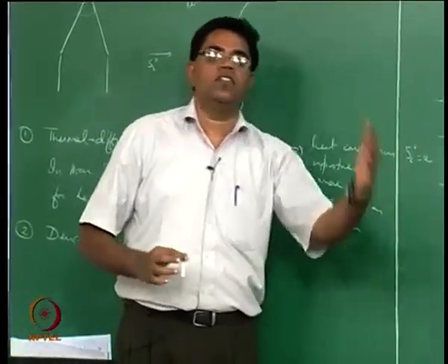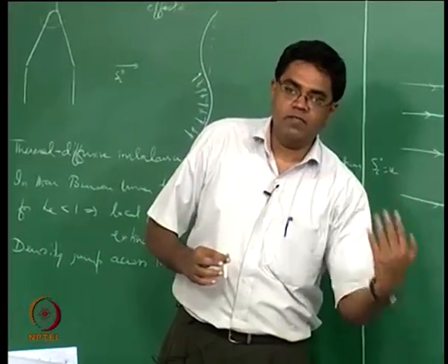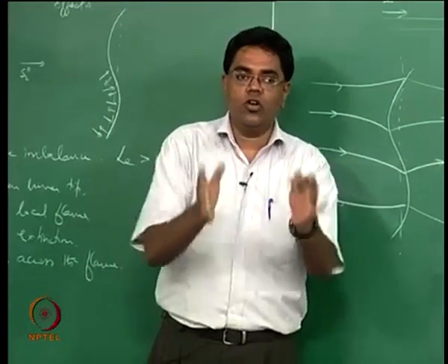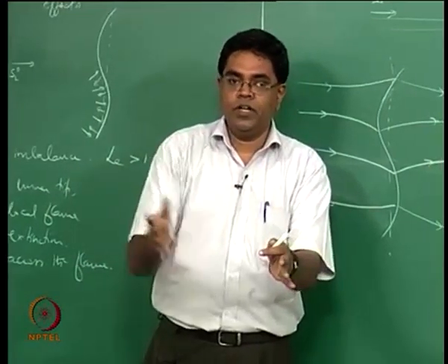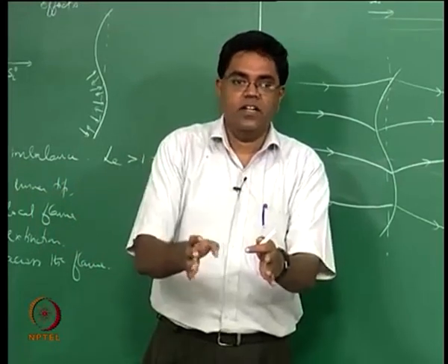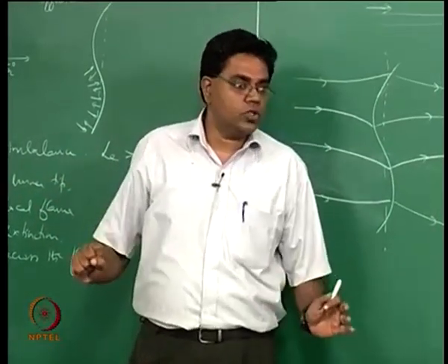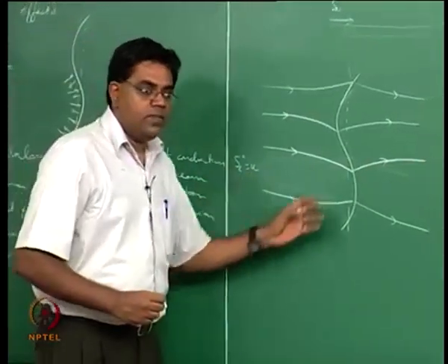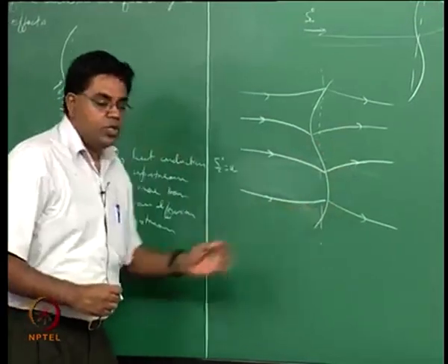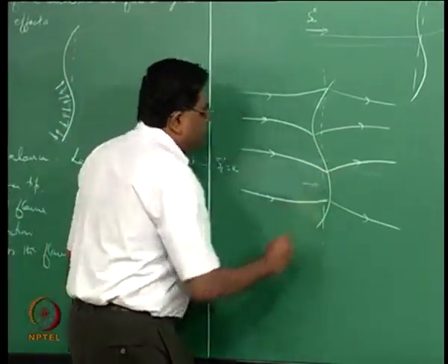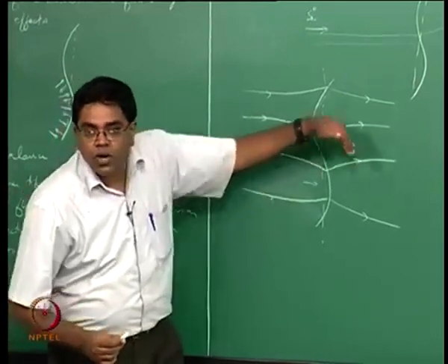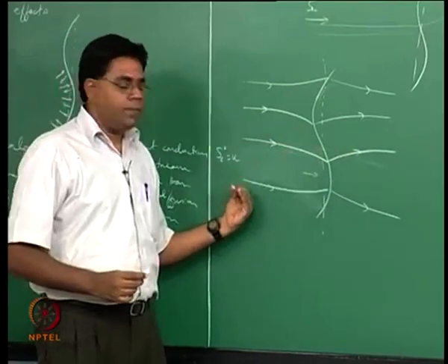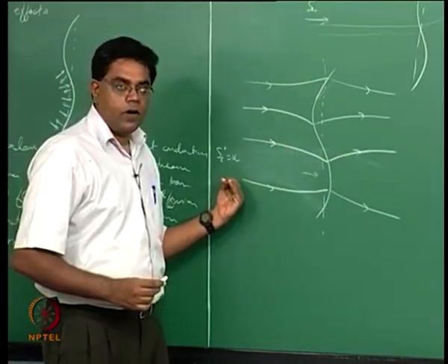What is meant by approximate is that it is stationary there, I can actually have a flame fixed coordinate system. What it is doing within the flame fixed coordinate system is not of concern to me so long as it is there. And what is the flow speed at which it is there is what is the flame speed, is what I would like to think about. So if I want to say that this is what it is, then what is the problem that is happening near the flame? You now find that the flow is locally accelerated when you have a flame that is curved concave relative to the far upstream reactants.